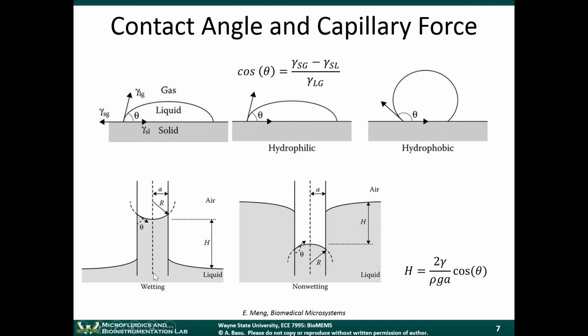If you have a hydrophilic surface and the liquid happens to be water, then the curvature of the interface of the capillary will look something like this, and the water will rise inside the capillary. This is what we saw on the previous slide. And then this diagram also shows if you have a hydrophobic surface, the opposite effect will happen. You could dip the capillary into a liquid, and it will actually try to resist the uptake of liquid into the capillary. And you'll have the exact opposite situation here. In both cases, you have the same formula that applies. It's just an inverse problem here.